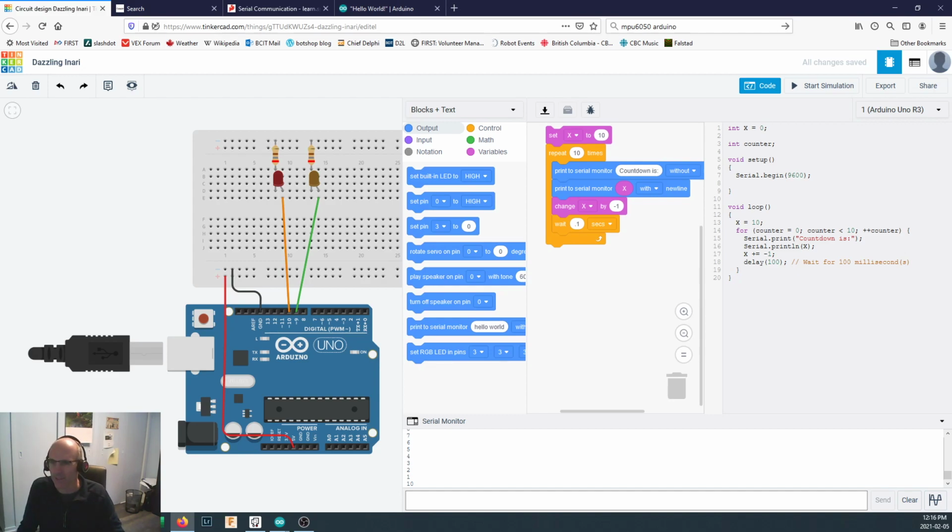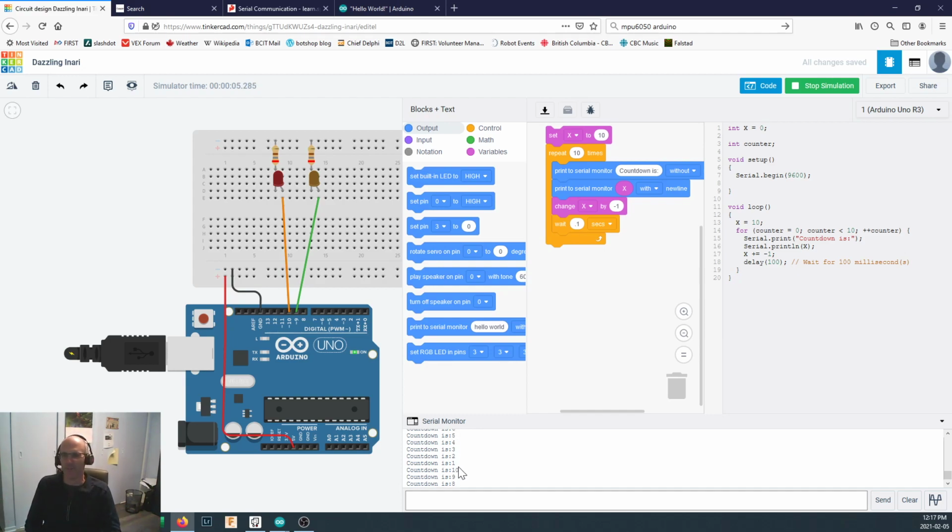And then it's going to execute this command. It's going to go and it's going to find whatever value is being stored in the X character. And then it's going to start counting down right in here one at a time. And let's see what we get. And now we're getting text describing what's happening, and then the number coming along right after that. It's not so difficult. If you can do that, what you're actually doing is a fairly sophisticated communication protocol, and you could take some fairly long wires and send that data down the line for a long distance.